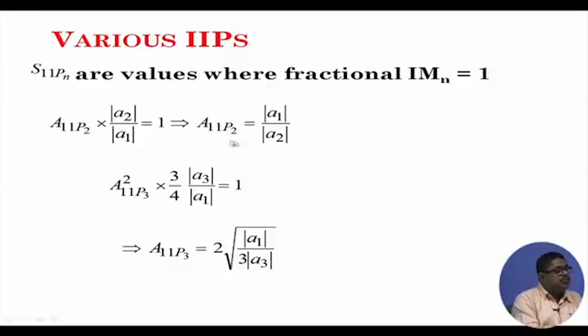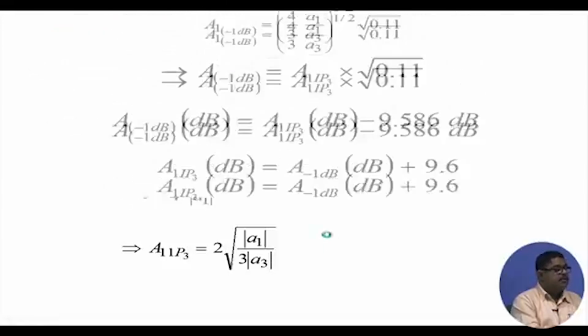So, I can do that because already we have done that intermodulation thing. If you do that, you see that at this value the second order intermodulation is becoming equal. So, this is the value where the second order intercept point is coming. Here the third order intercept point is coming at this value. So, this is given by A1 by A2, this is given by A1 by A3. A1, if you remember, is the linear part, A2 is my system coefficient for second order nonlinearity, this is third order nonlinearity.